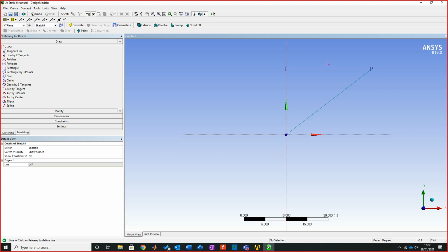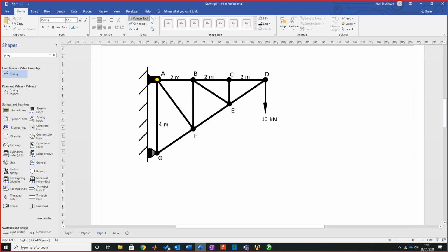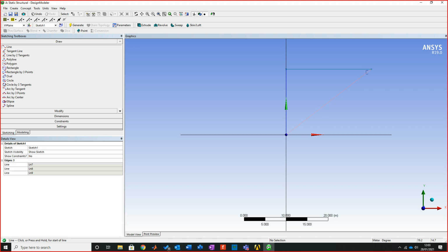So I'm going to left click again, because you'll see now I'm on the key axis component of Y. You can see it's glowing red. So I'm going to left click, and then it finishes the points. Now what I want to do is do one more line from there to there. See the V that's already been marked, so it's telling me now it will be a vertical line when it's applied. And that is the overall outside. So quickly on this geometry, we know it's 4 by 6. This will move in its key movement just because of how these are all connected. I'll come back to add the other lines in just a moment.